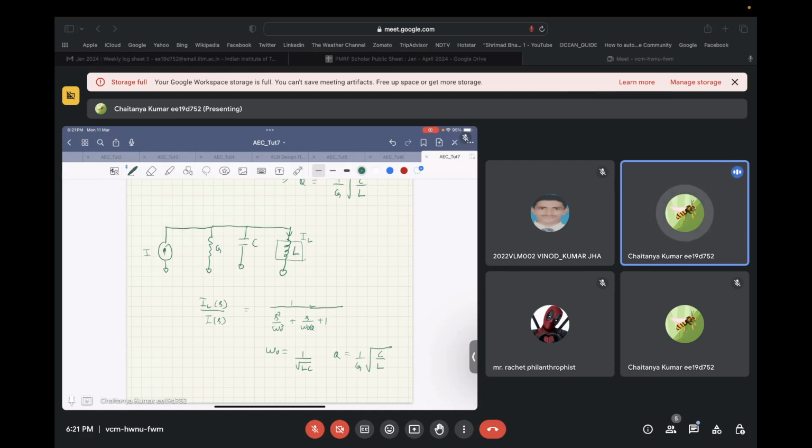frequencies. So when building wide-band circuits, you generally tend to avoid inductances, and especially at very low frequency, the value of inductance required will become so huge that it is not feasible on an integrated circuit. Typically, we can build inductance in terms of a few nanohenries on the IC, but not more than that. So what we do is,